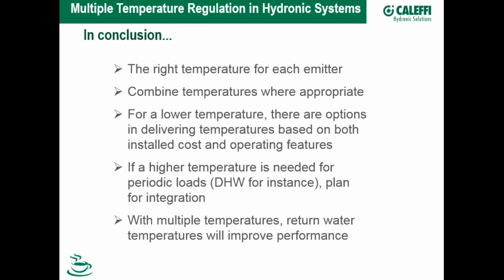And of course, the flip side of things, somebody says, how do I be more efficient? One of my first responses is always improve your building envelope. If I can drop the amount of heat that's coming out of my building, then I don't have to put as much heat into it, and I can be more efficient from that standpoint as well.